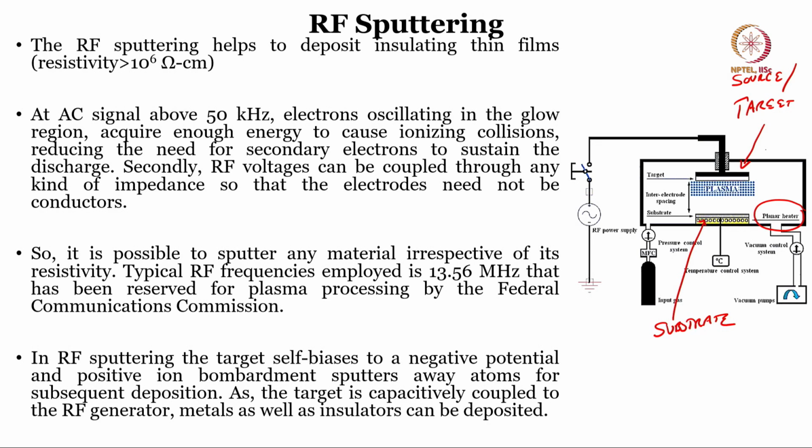You remember in thermal evaporation it was a very fast rate of deposition, that is why the atoms would have very little time to rearrange themselves. Here we can use heating to rearrange the atoms, and this kind of heating will affect the overall film properties for the better. For example, if you want to grow a piezoelectric film, heating the film during deposition will give us a better orientation of the film.